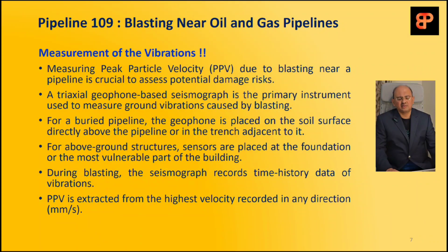For buried pipelines, the geophone, or sensors in simple words, is placed on the soil surface directly on top of the pipeline, or at a certain distance inside the trench, at a certain distance from the buried live pipeline.